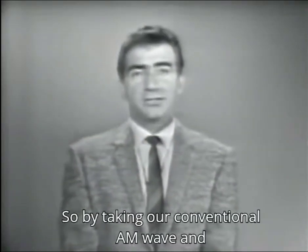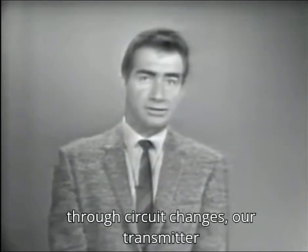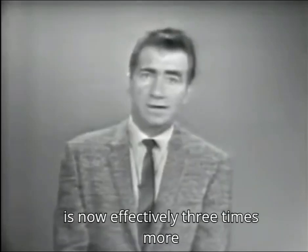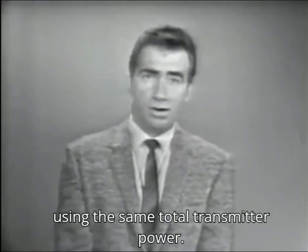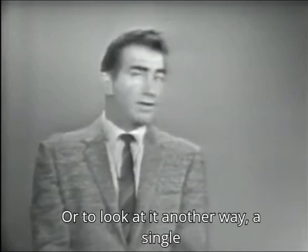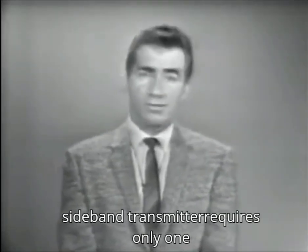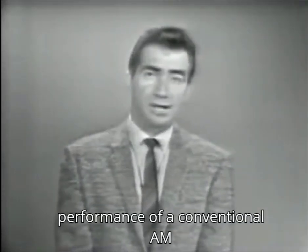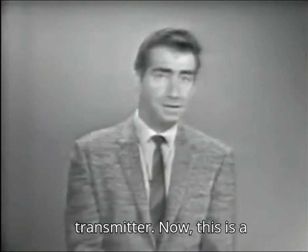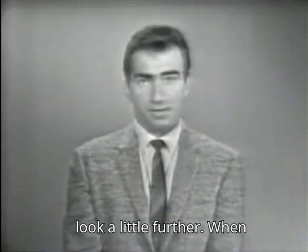So by taking our conventional AM wave and just rearranging the power quantities through circuit changes, our transmitter is now effectively 3 times more powerful than before, using the same total transmitter power. Or to look at it another way, a single sideband transmitter requires only 1/3 the power to equal the performance of a conventional AM transmitter. Now, this is a tremendous advantage in itself, but let's look a little further.